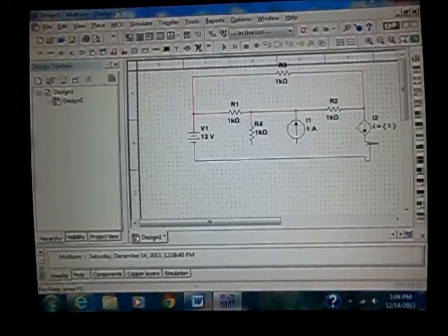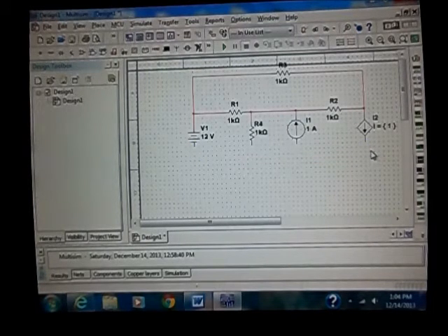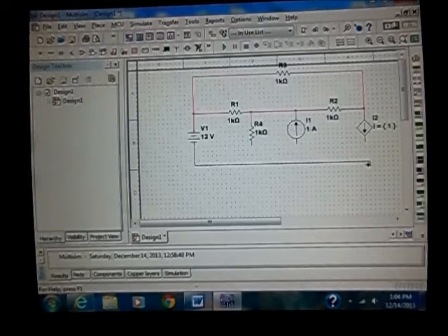Oh, well, that didn't look so good, did it? So whenever you have an error like this, I'm going to click on that wire that I don't like because it got ugly, and do it again. Sometimes that happens. Let up, press down, and I want to stop right there. Let up, press down. You don't always have to let up and press down. Sometimes it usually bends where you want it to. And then don't forget to click when you get it to its destination to actually connect the wire with a little connection dot, as you can see.